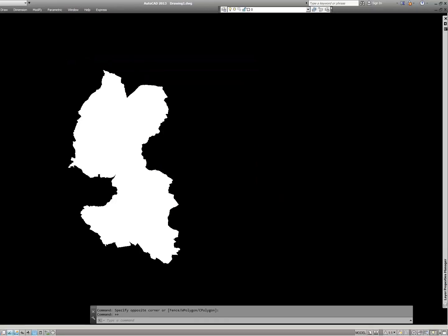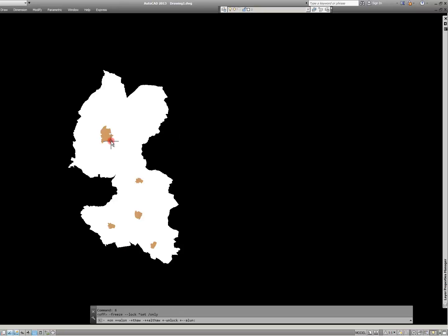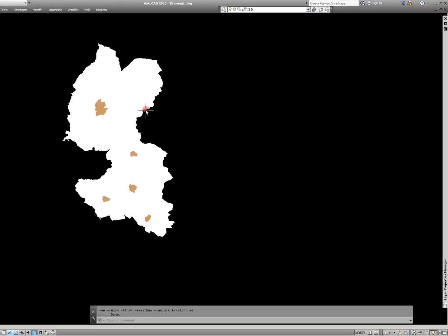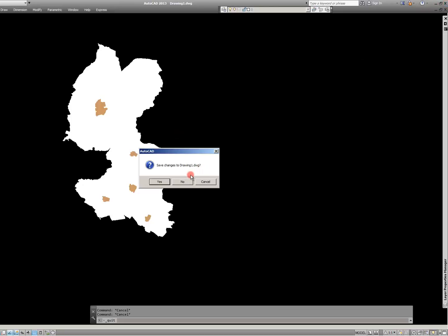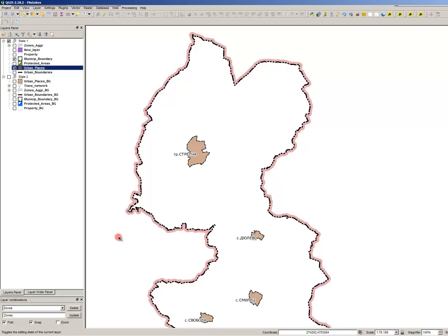Again, drawing 1, edit, paste original coordinates, and that's it. You have two different layers for the two QGIS layers, and you may of course turn one on and off like that, and it's very useful. You must know at least the basics of the programs your colleagues are using, so that you may interact more productively.